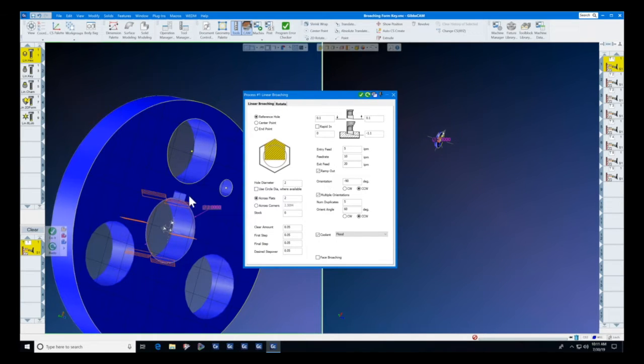When the broach goes to the bottom of a blind feature, it gets to the bottom, it simply pulls out horizontally, snaps the chip off, and then you're using either high pressure coolant or air to blow those chips out of the bottom of the hole, which allows us to continue broaching to the bottom of that blind feature using this one click button and redo and ramp out, and it will snap each chip off as it makes it on the way down.